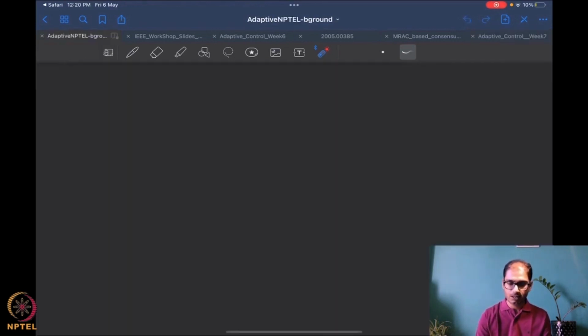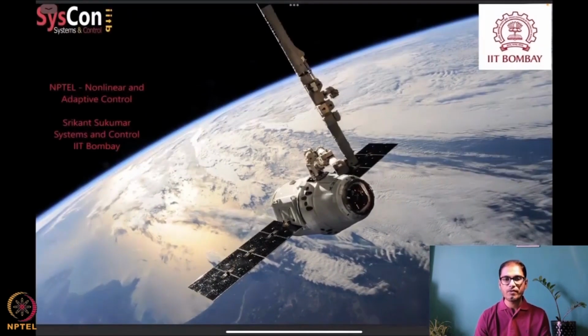All right, excellent. So what did we look at today? We started to look at backstepping in adaptive control, and we started with the non-adaptive problem. Until now, we've done the non-adaptive problem, and we've seen how backstepping control is actually designed. Essentially, backstepping is a way of constructing additional Lyapunov functions by augmenting the Lyapunov function corresponding to each state. And that's what we did. Started with the E1 state, created a Lyapunov candidate, and then we moved on to the E2 state. So that's the idea of constructing these Lyapunov functions.